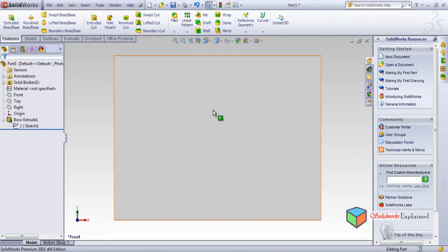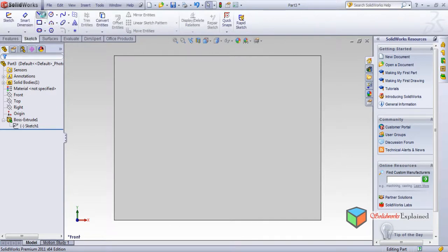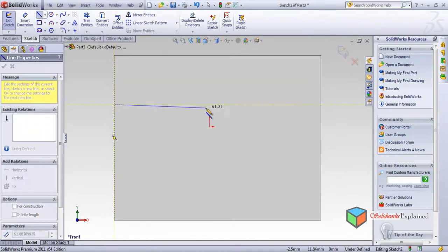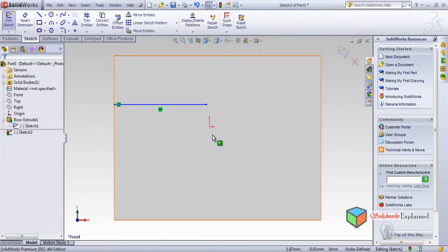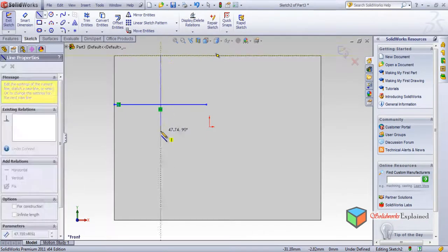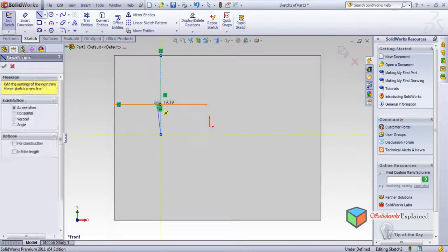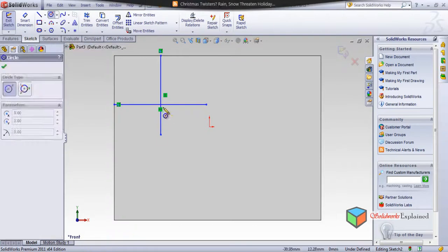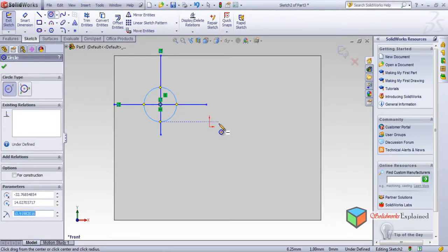I want to draw a circle, okay, and for the circle I want the x and y, the point. So where I want to make a circle, it's difficult for me. So for that, what I'll do is go to sketch, click this face, and I'll make a line like this, escape, again I'll make a line like this. Okay, now I got the center point of it from which I can make a circle. So I'll make a circle from this point. Yes, I made a circle.